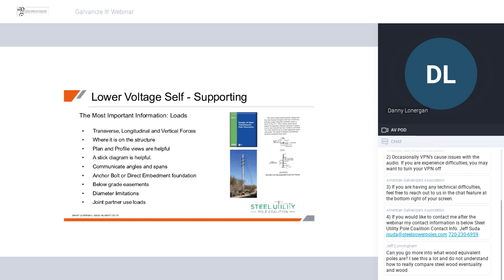So the right-of-way definition below grade is usually what governs the sizing of a pole and/or the construction preferences of the installer. The hole can't be larger than this due to underground right-of-way, other utilities, water, power, gas, whatever it might be. Another item that is usually a struggle to capture is third-party connections. That's generally a challenge for anybody who owns the pole. Any given utility understanding their third-party connections is always a topic of debate. Again, the software helps with that.